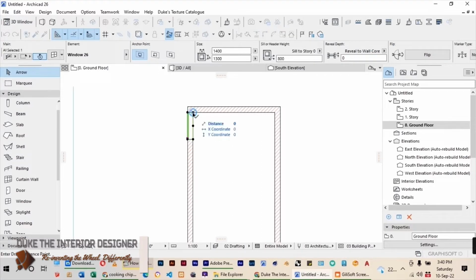You need to know the shortcuts. I'll use Ctrl D for moving, let's move. I'll use Ctrl M for mirror, Ctrl E for rotate, and Ctrl U for having multiple objects. Whenever you do Control something and then Control, you create a copy.